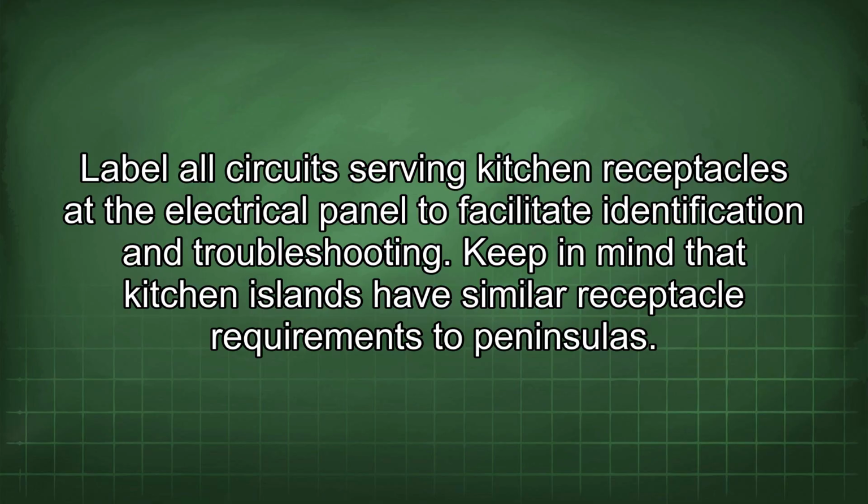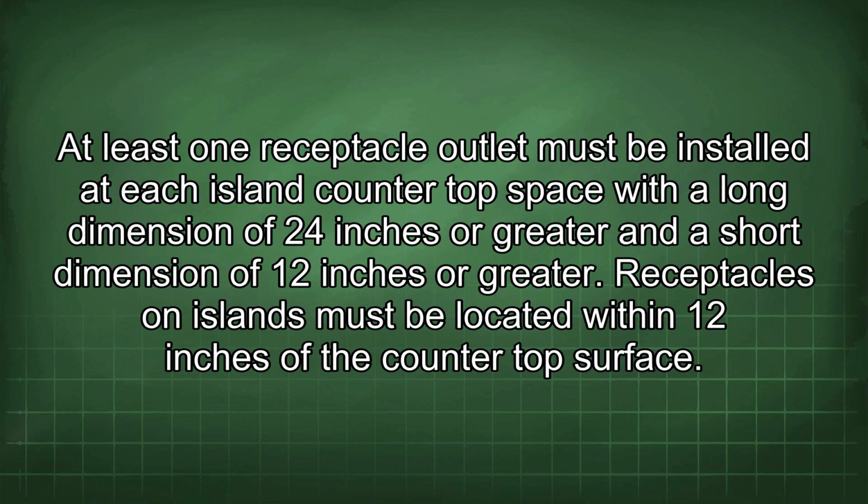Keep in mind that kitchen islands have similar receptacle requirements to peninsulas. At least one receptacle outlet must be installed at each island countertop space with a long dimension of 24 inches or greater and a short dimension of 12 inches or greater. Receptacles on islands must be located within 12 inches of the countertop surface.